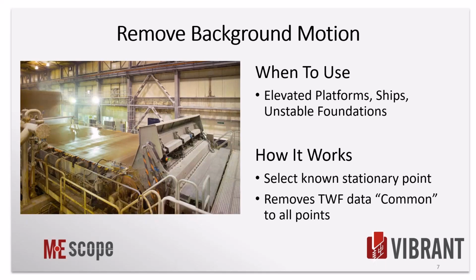So we're strictly getting the vibration and the ODS of the structure or the machine itself. And then unstable foundations, all the same concept there. But like we talked about, the way it works, you get in there, you want to select a known stationary point in the video. You can do a single point, you can do several points, you can grab a group of points there.